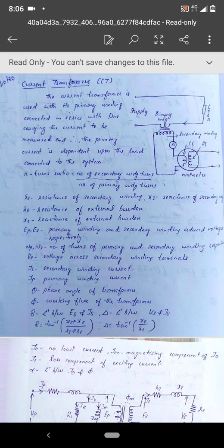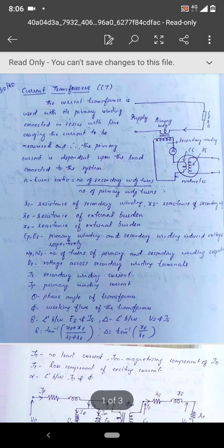One of the reasons is that for AC measurements, since the current carrying coil is stationary, you can measure straight away. You can measure up to 50 amperes. So there is no need for shunts, and the shunts and series multipliers have their own disadvantages. I have discussed them, and I have given a material so that you can read and understand.